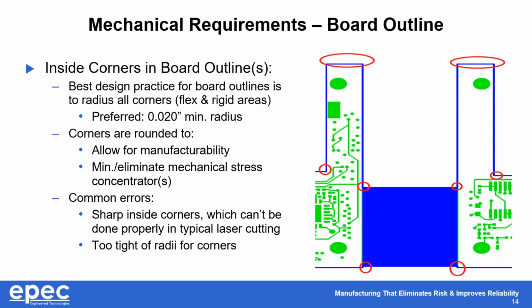Most common errors we see for these are sharp inside corners, which can't be done properly with typical laser cutting, or that we end up seeing too tight of radii, which ends up being almost similar to a sharp inside corner.